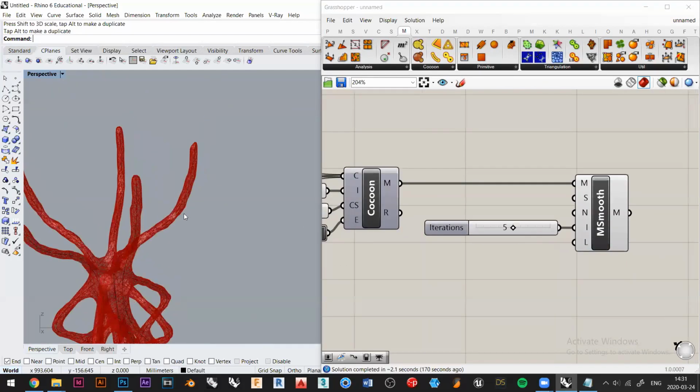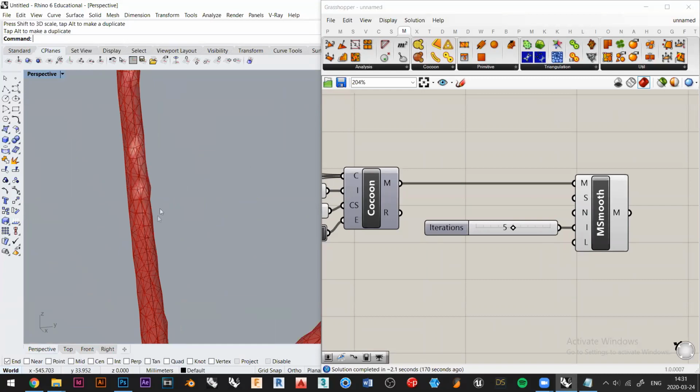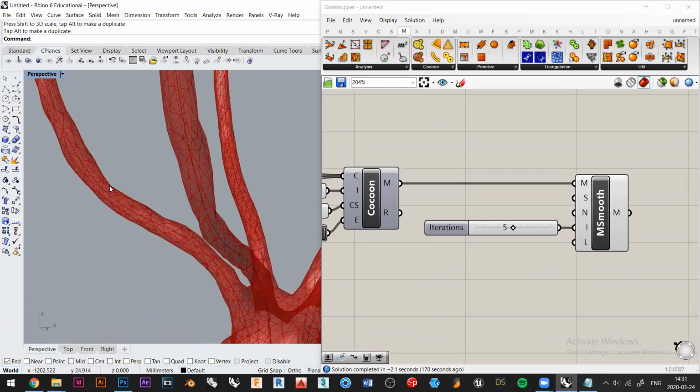And there is a limit for maximum change in the structure, but we don't care about that limit. So we can see here that even though we are using smooth, it's not smoothing it out that well. And that is because the polygons of this geometry are arranged in a very funky way. And it cannot smooth it properly because the topology of the geometry is not great. While it is a perfectly 3D printable geometry and it's clean in that regard, the topology of it is not clean. So the arrangement of the faces is not clean.